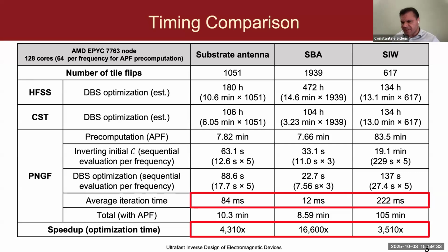To answer your question about the surface roughness, we don't have a particular surface roughness model that we're considering. However, oftentimes we'll consider surface roughness as an additional loss. And so if you have a way to map the surface roughness to effective epsilon or conductivity parameters, then we can very easily map that into what we already have. If you have a different way of representing surface roughness, then please talk to me. I would love to learn more and see if there's some way that we can extend our method to consider that further. Okay, great. Thanks.